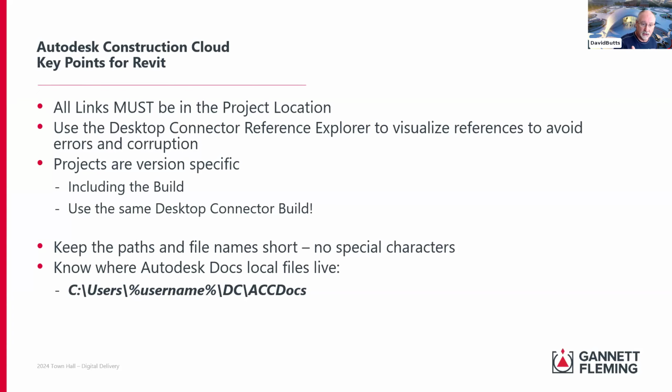Now, to help you with this, if you're working in the cloud, another great myth: desktop connector is required for you to work in ACC docs. Don't think that it's not. You might not be using Revit, you might be using AutoCAD, you might be using something else, but you absolutely want to have desktop connector installed and running, because that tool is actually the local cache version, and it exposes the local cache version of all the files that you have in the cloud.